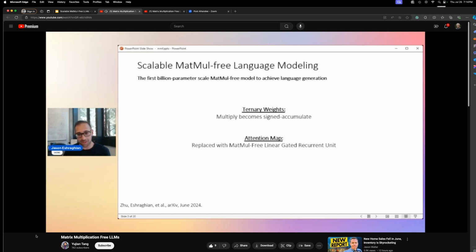So we call on the hardware engineers of the world to go ahead and optimize low bit width operations and more lightweight LLMs. So yeah, we took that up on ourselves and built our own FPGA implementation of this model as well. And as a result, we were able to run this model at 13 watts with human readable throughput.